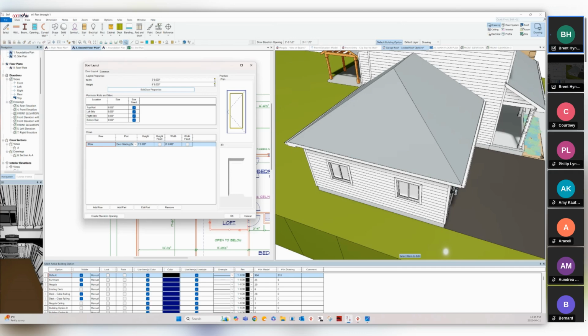Currently, if I was to put a 3-foot door in a wall and then make it 5 feet wide, it's going to stretch that thing all the way across equally. So the stiles and the rails will all get bigger as we go across. With the parametric openings, we can control which items will scale and which ones will remain fixed. All right. For those of you who are familiar with wall definitions, same thing as making your plates fixed versus your studs adjustable.